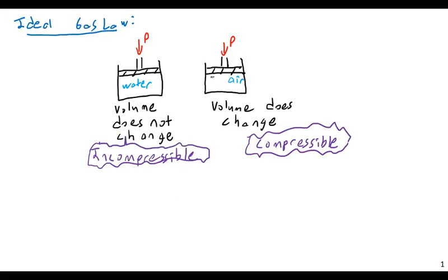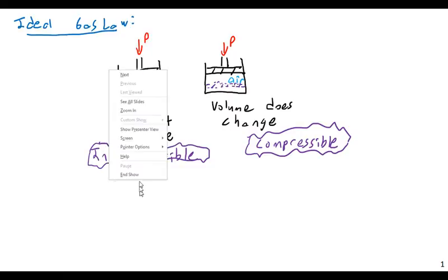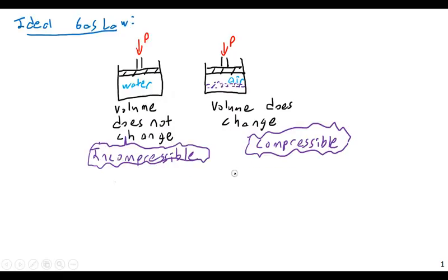So when a force is applied, the piston will end up going down, and all of the air will end up down in this little pocket. Based on the pressure P applied to a volume, the volume will change, and the density of the gas thus changes. When you have a sealed container and you apply pressure to it, the density of the gas will actually increase. And there is a simple expression for the density of a gas, related to both temperature and pressure: rho gas is equal to P over RT.